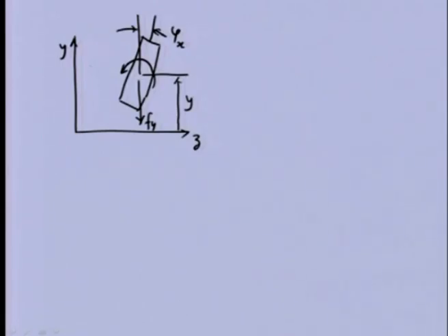that is reaction moment on this plane, that is M yz, which will be acting opposite to the tilt, because the tilt in this particular plane is in the clockwise direction. So, this moment will be opposite to that, in the anti-clockwise direction. Similarly, displacement is in the vertical direction, so force will be in the downward direction. This is the reactive force from the shaft onto the bearing.